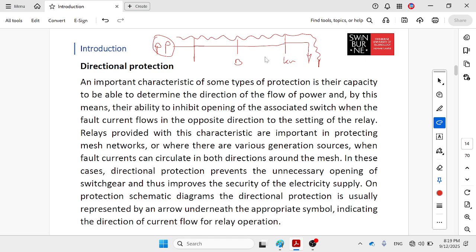In the case of the new power system, in which we install PVs, wind farms, wave energy, whatever, renewable energy considered, if we can generate energy by these two, this energy can return back to Bintulu, correct? So the direction is already changed. The one-way road becomes double-sided. So it is very important for the relaying system to know how the flow is.